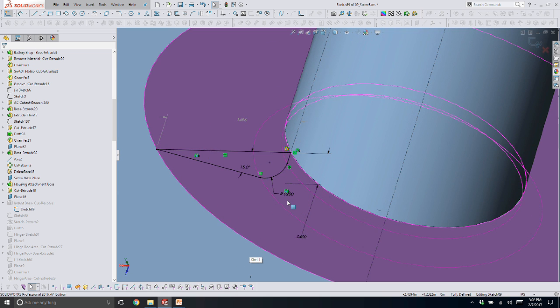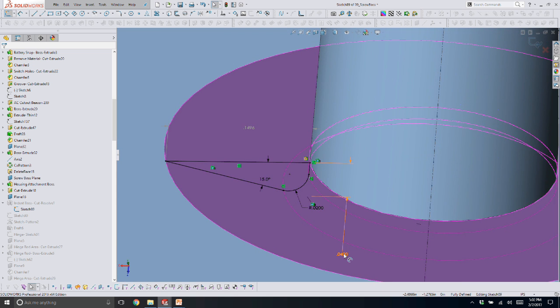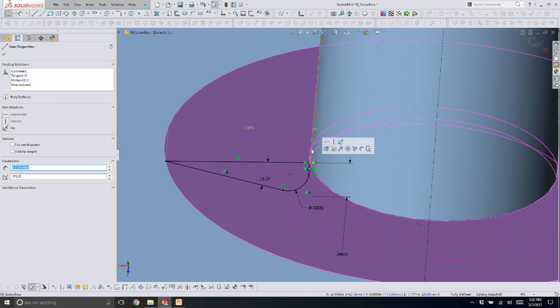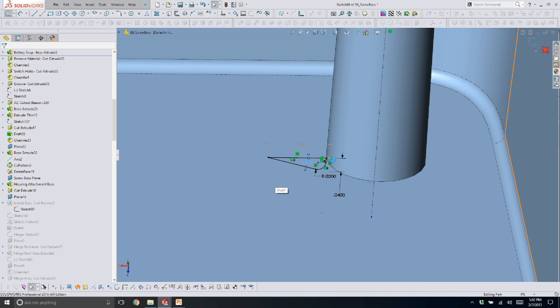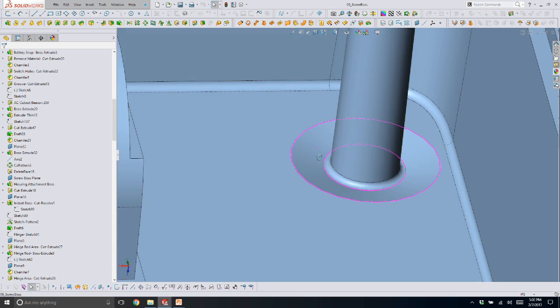And then my little sketch here. So here I'm going down 40 thousandths, 40% of the nominal wall. Added this line collinear here, a little bit of a fillet on the bottom. And I see these details at between 15 degrees and 20 degrees. What this is going to do is just limit the material you've got going on.